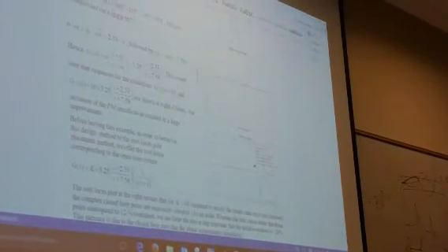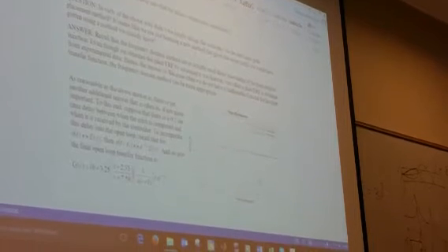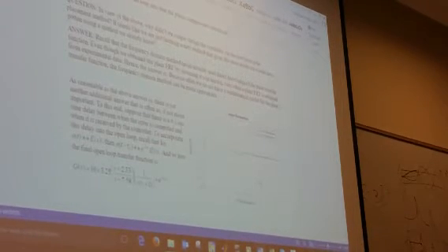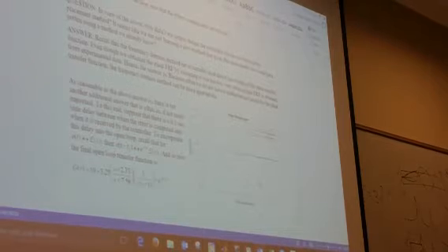And this one is with and without the time delay. So it looks like what the time delay did is brought us back to square one. It's like it canceled out the effect of the compensator. We're now back to an oscillatory step response.